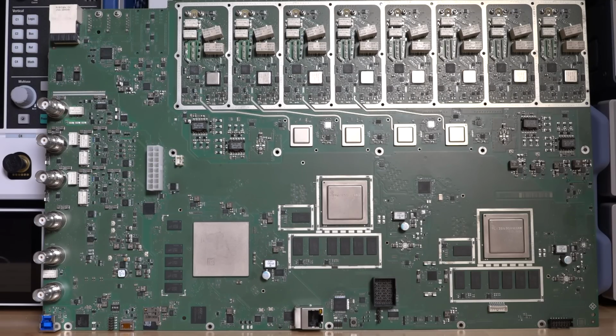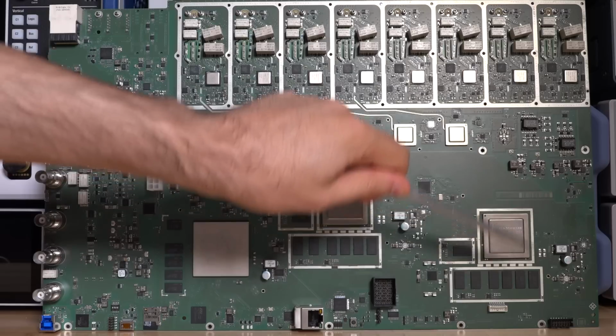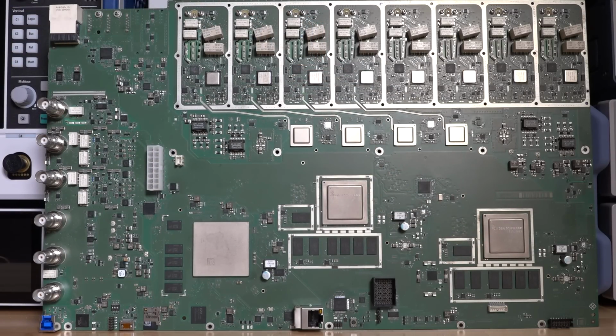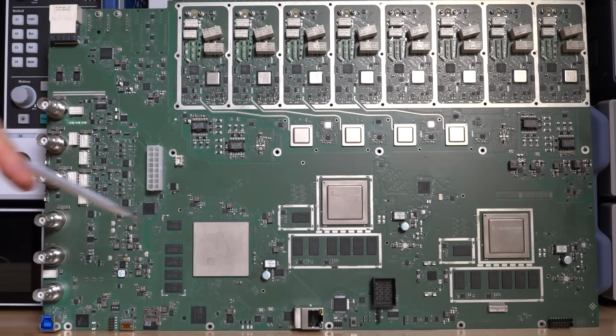And there's some hardware replication, which is immediately obvious. For example, this section over here and this section over here, they're essentially the same. And you could make two MXO-4 series with those sections alone. At the same time, you have the front end and everything fully custom designed, and everything is self-contained. So the acquisition, the triggering, the ADCs, and so on are basically their own subsystem. So putting them next to each other is somewhat easier. The only thing that's shared is this Xilinx Zynq FPGA with its own memory and so on, which is basically interacting with the entire system.